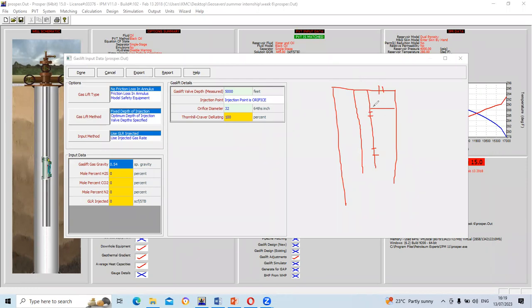and then flow to the surface. Then the gas will push the liquid level down below the valve. Immediately it comes below the valve, this pressure becomes higher and the valve closes. You keep pushing until you get to the next unloading valve. These valves also open and the fluid starts flowing. So you get to a point where you have unloaded all of the annulus and the liquid level is now below the operating valve.